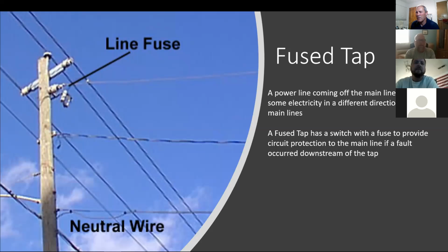Yeah, I looked at that. That's a cable, that's cable TV or telephone. So the picture's labeled wrong. Not your fault, Willison. Some companies do this, and it's kind of dangerous. There is a neutral wrapped up in the secondary, and they'll use the neutral for secondary and primary in this span, and that's not a good practice.